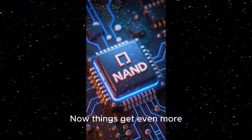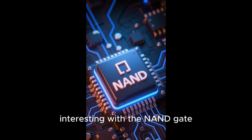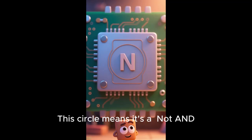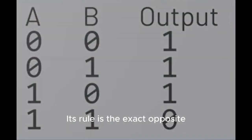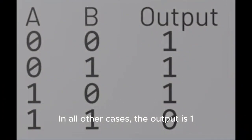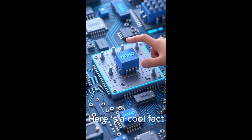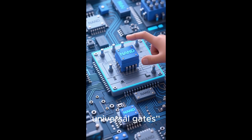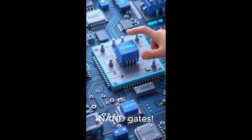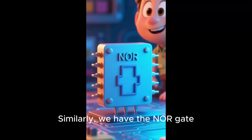Now things get even more interesting with the NAND gate. The symbol is just an AND gate with that same little circle at the output. This circle means it's a NOT AND gate. Its rule is the exact opposite of the AND gate. The output is 0, or false, only when all of its inputs are 1. In all other cases, the output is 1. Here is a cool fact. NAND gates are called universal gates because you can actually build any other type of logic gate using only NAND gates.